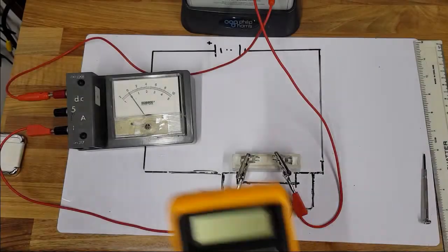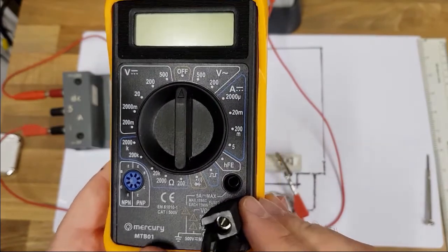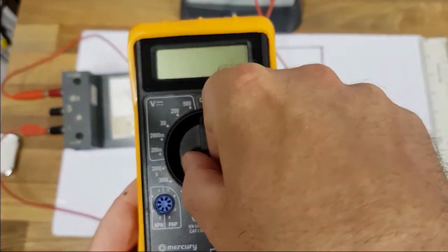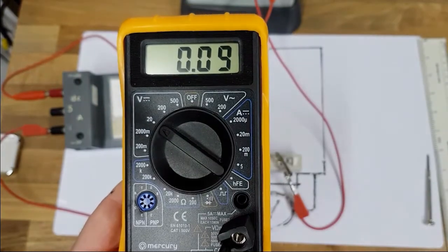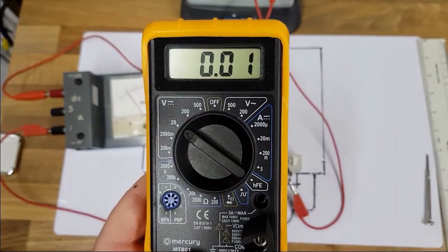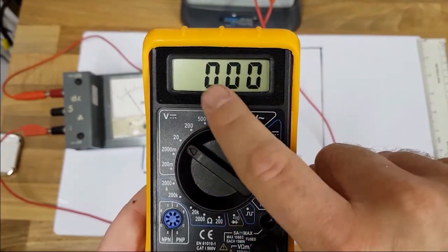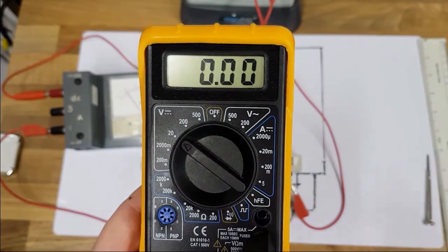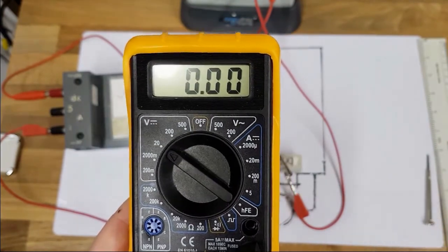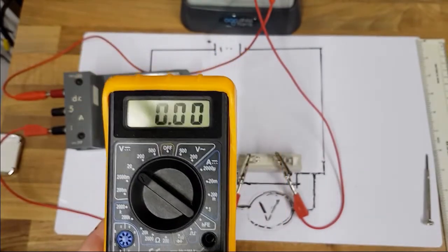Now, here is a multimeter, very similar to the ones that we have in school. I'm going to set it to 20 volts direct current. This is the voltage, or the potential difference, that we're going to be reading on this occasion, and that number 20 means that the range displayed on this dial is going to be between 0 and 20 volts, which is perfect for our scenario here.